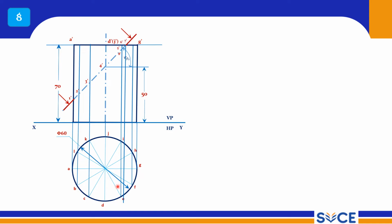Up to the E generator you have points on vertical generators, and then you have two more cutting points, point number 6 and 7, on the horizontal surface. Those 2 points should be projected and drawn, and the 4 remaining points should be drawn here. So totally 11 points I am getting here. All these 11 cutting points should be projected to show the cut surface. It is obviously a truncated surface.